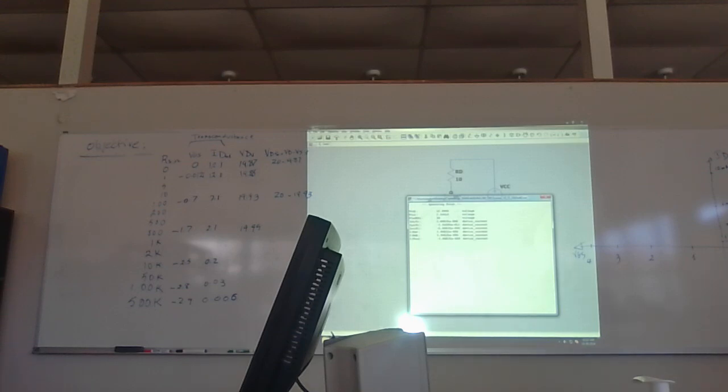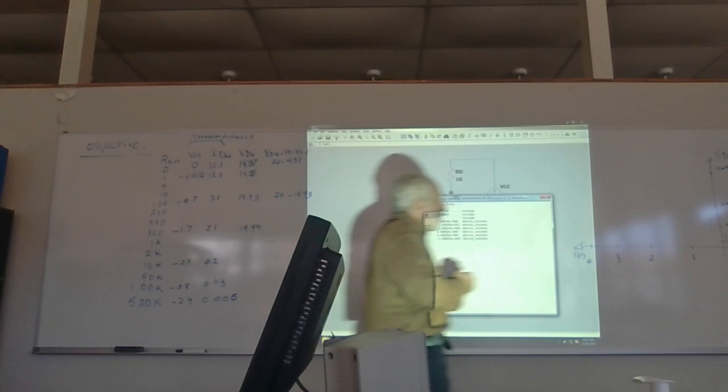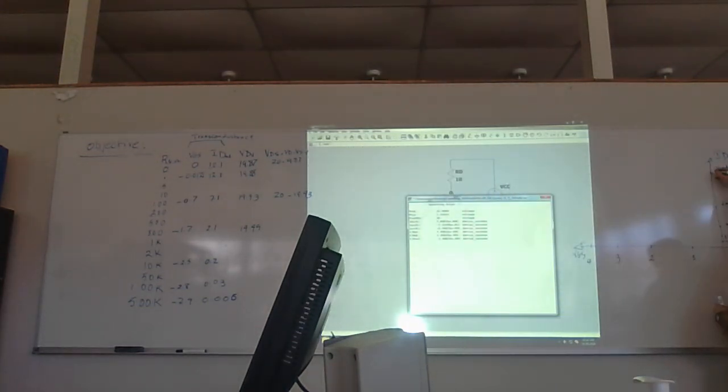Okay, and then I'm going to pick up a few points. I'm just going to draw points first. At 0, I'm here at 12 milliamp. Here's 1 point. At 0.7 volts, which is about right here. So this is 0.5, 0.6, 0.7 right here. I have 7.1 milliamp. So 6. So I'm going to be right here somewhere.